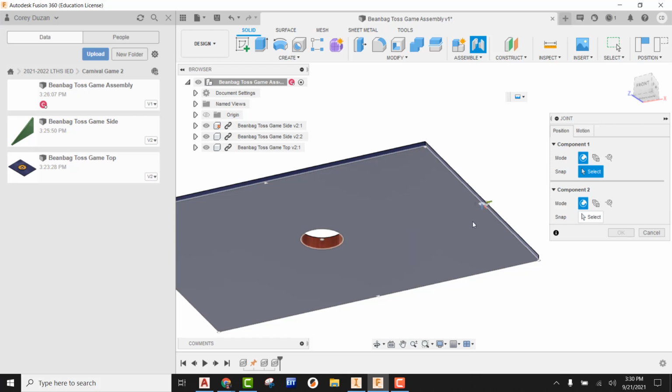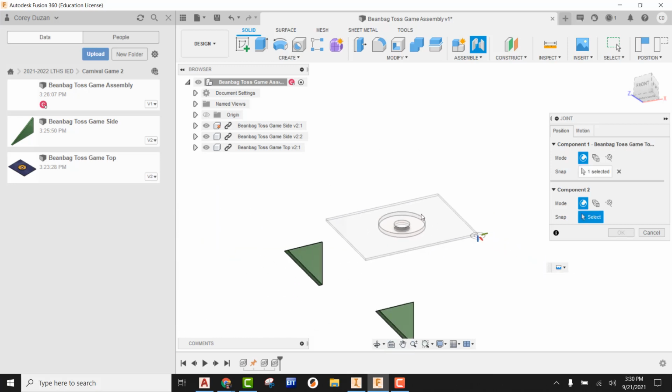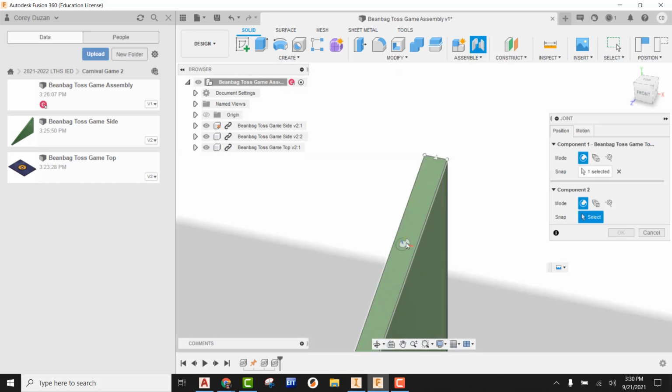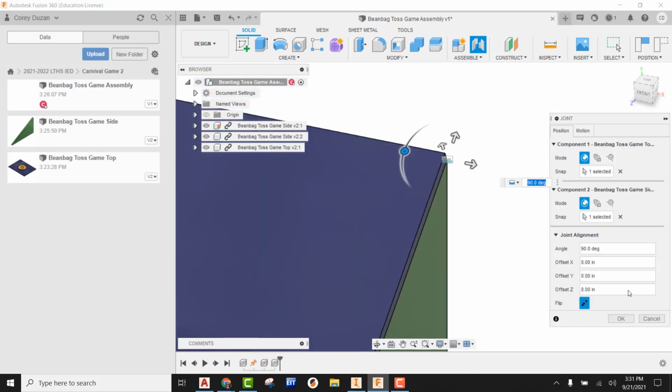So once I am seeing all those points showing up, I'm going to go to the point that I want, and I'm just going to pick. Now I'm going to use orbit, flip this over. Now I'm going to come in and bring into this surface. So I'm starting here in the middle of the surface. I'm going to hold down control. And now I'm going to start looking for those points to use. So I know that that point there is where that's going to go. It's going to come right into it.